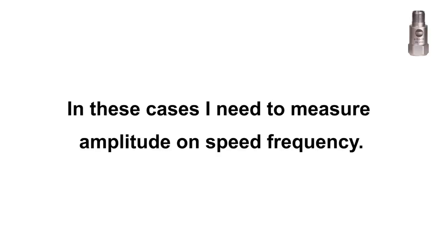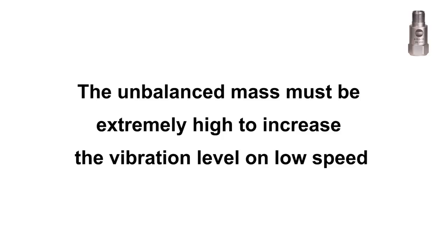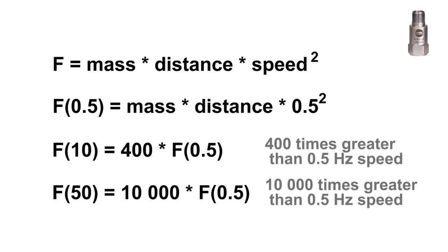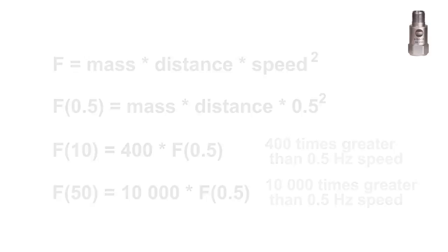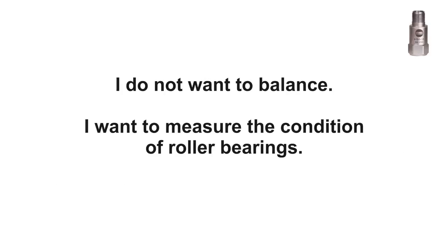When the speed is such low, then you should have the unbalanced mass tens of kilograms to increase the vibration level. The centrifugal force depends on power of speed. On 30 RPM, it will be very low. But the users say, no, I do not want to balance. I want to measure the condition of roller bearing. And this is the key point.